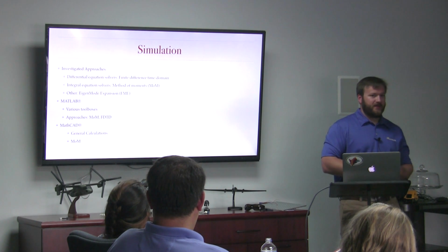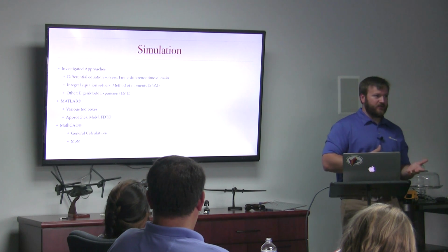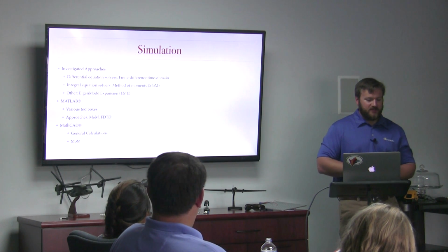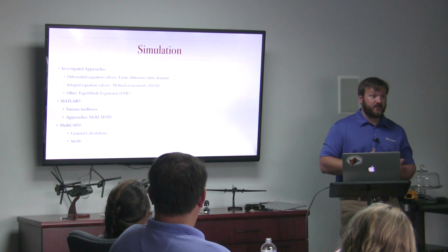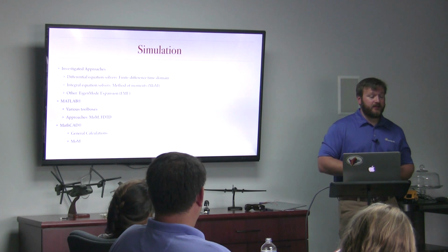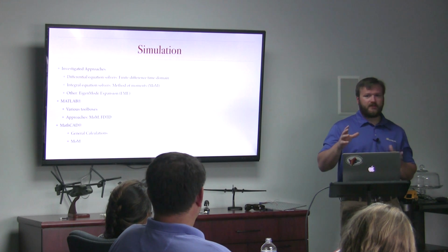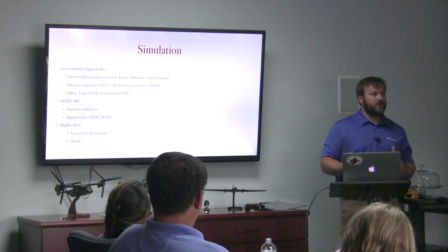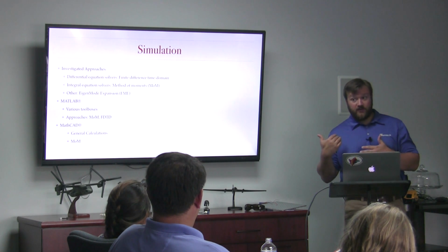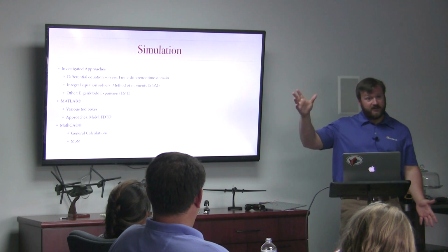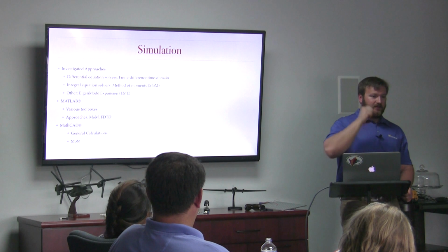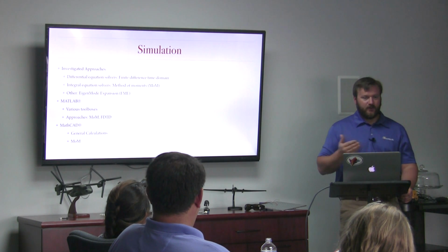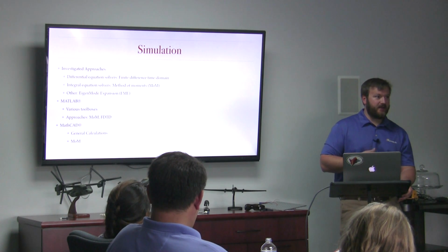There's the finite difference time domain method, which is one of the differential equation solvers, not very easy to do something out of the box on your own. Method of moments is a very applicable way for this application of producing a good simulation of the radiation pattern. Anyone familiar with EM solvers at all? Depending on the frequency and the application, you can look at them as a traditional electromagnetics approach using Maxwell's equations. Method of moments is one that we do that with. Or at very, very high frequencies, well beyond this, you take an electro-optics approach, looking at incident, reflection, return. There are some EO things you can do at this frequency, but for determining what the pattern's going to be, it doesn't help us to think about it in an EO sense.